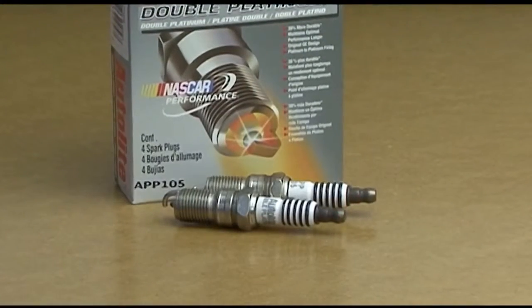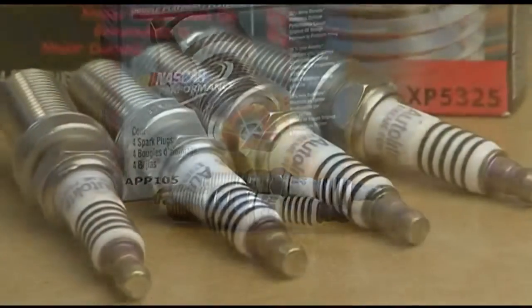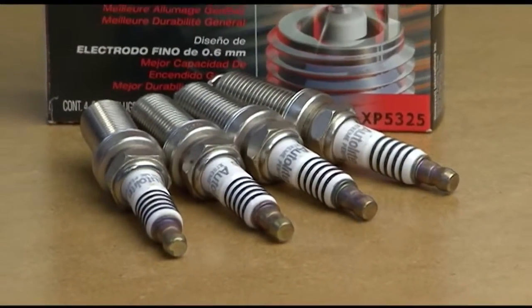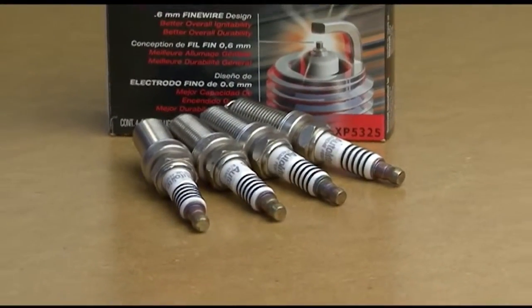You should always use a platinum or iridium fine wire spark plug in modern conventional or coil on plug ignitions. An Autolite double platinum spark plug or an iridium enhanced Autolite XP spark plug should be used in DIS ignitions. While it may seem like a bargain to use a copper core spark plug in a modern ignition system, it really isn't. A copper core plug will experience considerable gap erosion in as little as 18 to 30,000 miles.